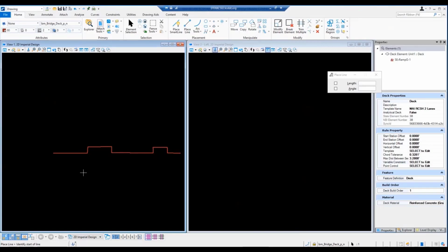I think you would have to keep all your corners as right corners, and then have the height defined from the chamfer of your bridge deck. You would define your 10-foot post here, have it be level, have it come down to whatever your cross slope of your bridge deck is.